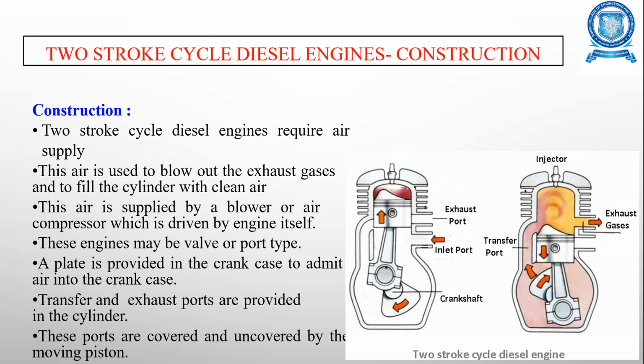Fresh air enters into the crankcase through this inlet port, and when the piston moves down to the bottom dead center, this fresh air will be passed into the cylinder through this transfer port. These three ports are covered and uncovered by the displacement of the piston.